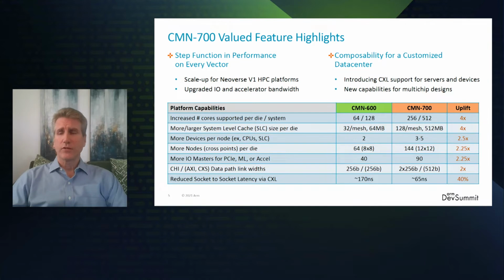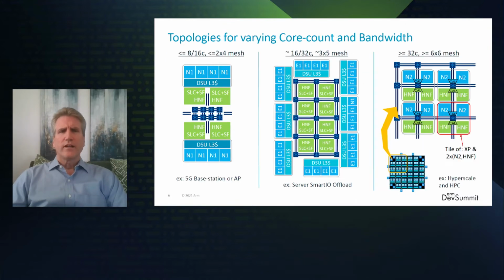As a general guideline for component placement, we advise placing the system cache, also known as a home node, and CPUs together around the interconnect and placing the external memory controllers and I/O on the outer edges. This provides the lowest average latency and good load distribution. For small configurations, like on the right-hand side, one could place the CPU clusters and cache outside the mesh fabric. The example here shows XPs at the center with very short mesh lengths between them. And there are like 4 system caches and Snoop filter instances in green and 2 CPU clusters on the bookends.